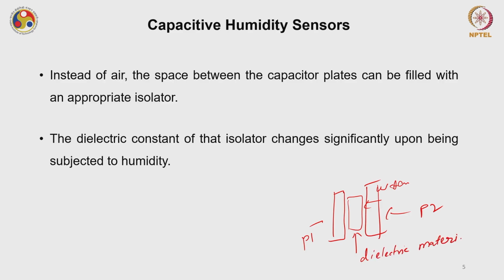Now what is happening is it is subjected to moisture. Say it was initially subjected to 25% RH. Okay, so at that time it was properly working. Now I have increased this humidity to say 90% RH. In such a high humid condition, if this material possesses very high hydrophilic property, what will happen is it will start absorbing some water molecules from this.